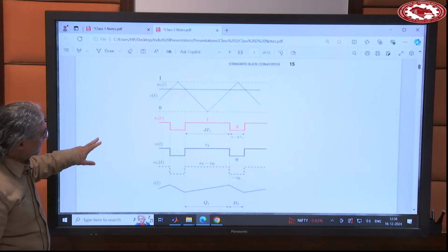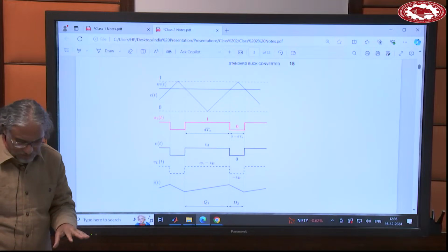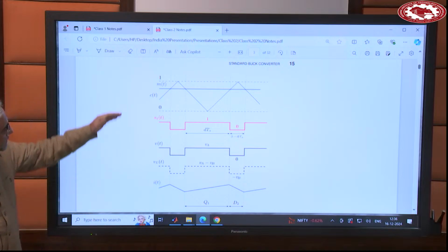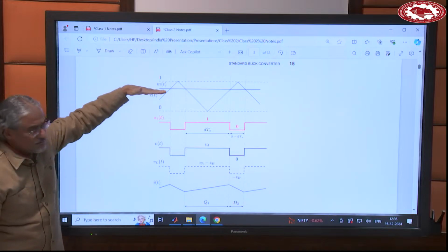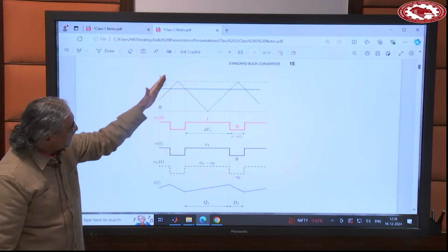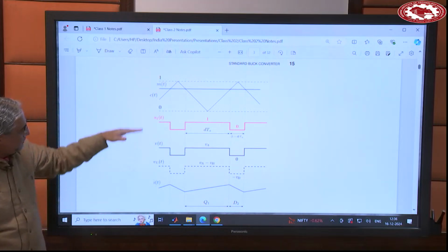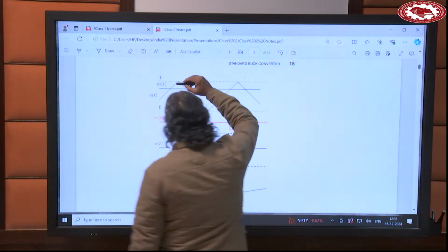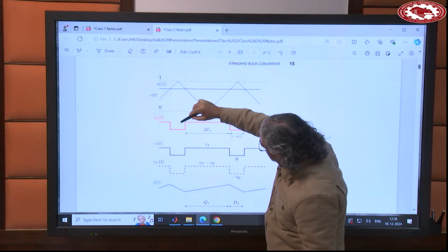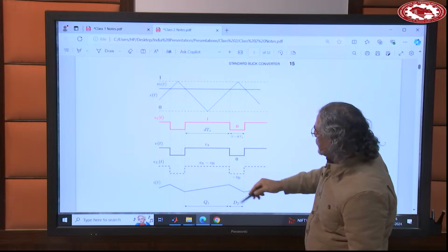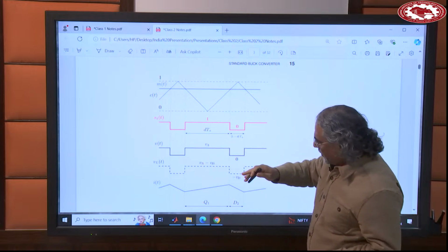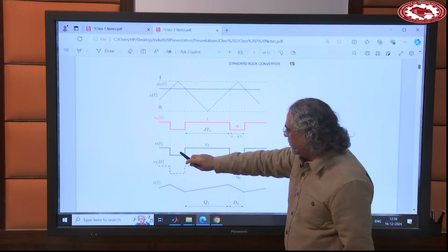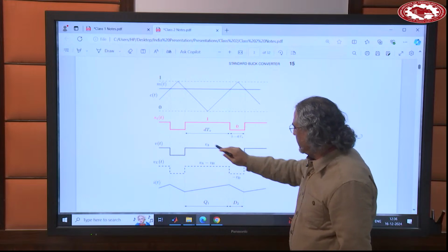So for instance, in the context of this buck converter that we just discussed, let's say m is a constant, right? And this is carrier waveform between 0 and 1. And then when m is again larger than c, you have 1, and then you have 0 here. So this is the voltage across the diode, which is either 0 or VA.